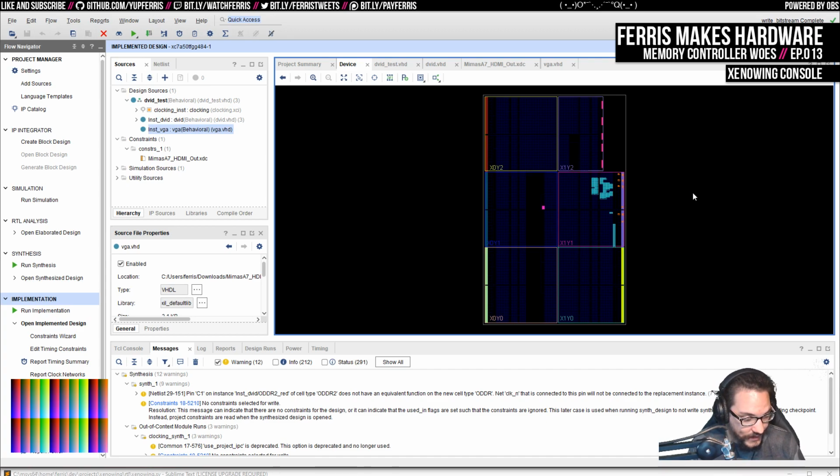because at least when using the Altera board, the equivalent feature, SignalTap, where you're adding this logic debugger to your design, and it handles all the plumbing associated with that for you, is extremely helpful to be able to actually see what's going on in there. So I would love to have that feature. It's not a deal breaker, but if I need to buy a somewhat expensive cable to do that on whatever Xilinx boards I end up buying, I'm going to do that because it makes a lot of sense.